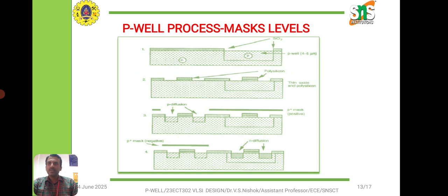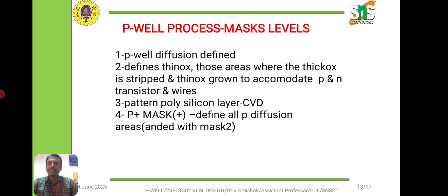And then coming to the IC fabrication, the CMOS IC fabrication process using the P-well process. Starting from the wafer preparation and step one, then oxidation, and then steps one by one: photolithography, etching, and up to the packaging.